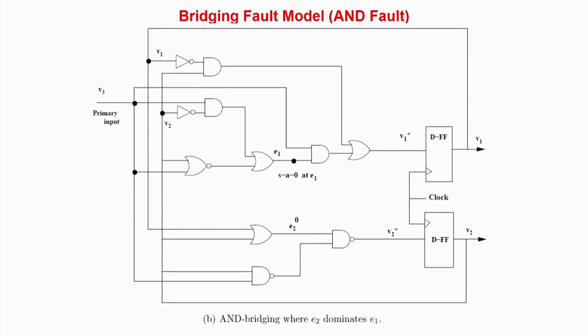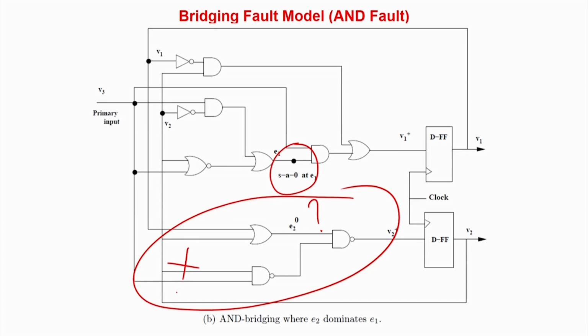But one interesting fact is that some people also try it in this manner. Say, if I go only for stuck-at fault testing, a stuck-at fault test over here, but some pattern will be applied over here. Of course, for me this region is X. In this case I don't bother what is happening to the circuit, but by chance this line may have a 0, or as you are not bothered about it, it may be either 0 or 1. So by chance if it is a 0, the bridging fault is by default tested along with the stuck-at-0 fault over here.